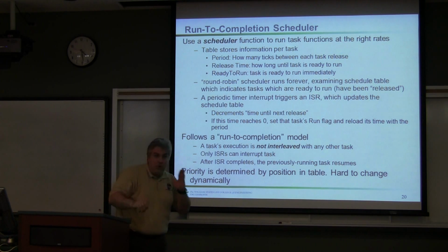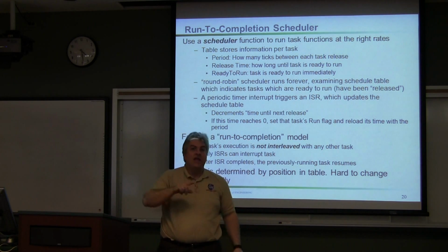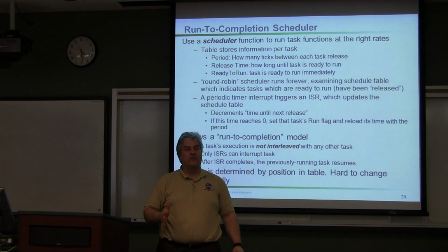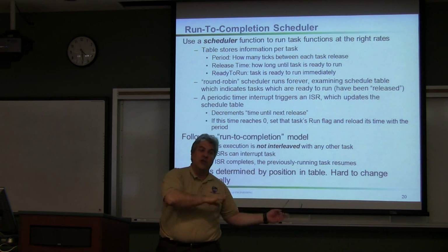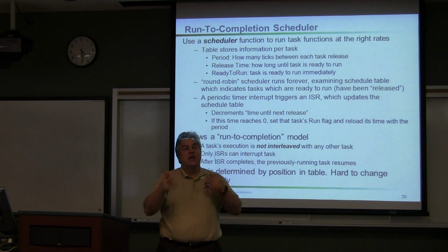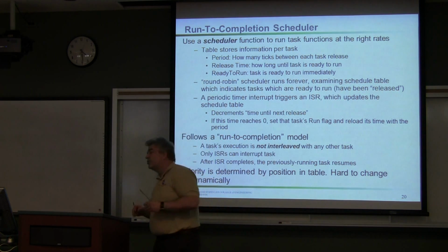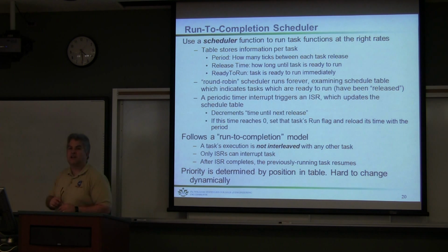What I'm pointing out is that at time n plus 1, n plus 2, at the beginning, right there, our algorithm says stop, go to an interrupt service routine, and start examining who needs to run now. That's what is directed and it's done in an interrupt service routine, which happens based on some periodic timer. In the first example we did, it was every 1 millisecond. In our little exercise we did, it was 0.5 milliseconds.